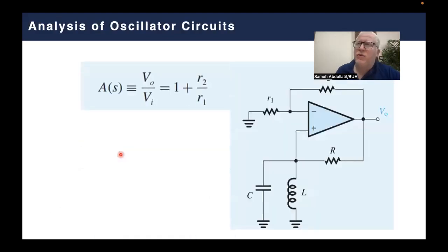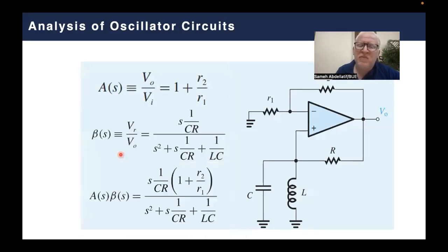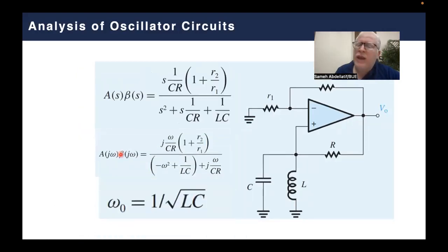We start with this fundamental circuit where we reach two main constraints. The first is that physically it is not applicable to reach a typical A beta equals 1 due to this R1 over R2, because in order to reach an A beta equals 1, you have to set R1 over R2 equals 0, which is practically impossible.